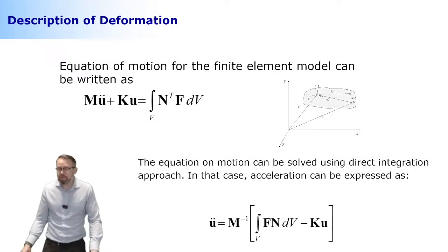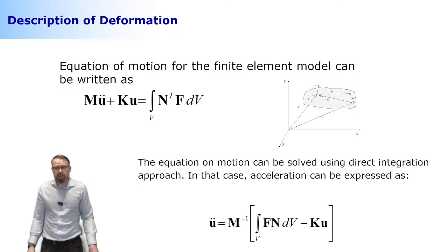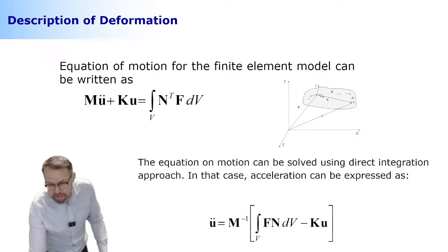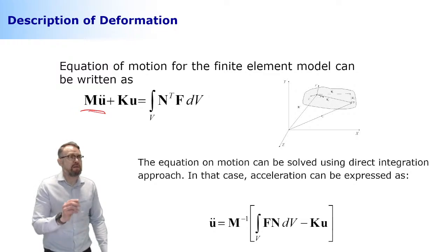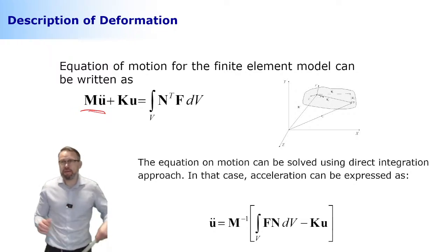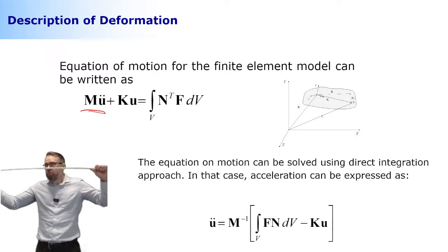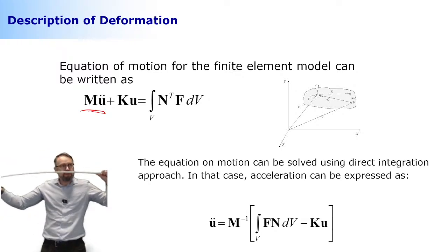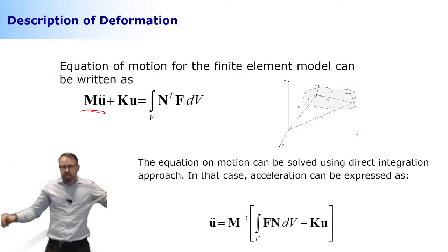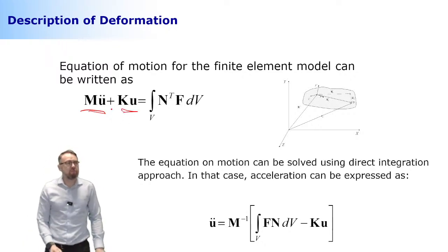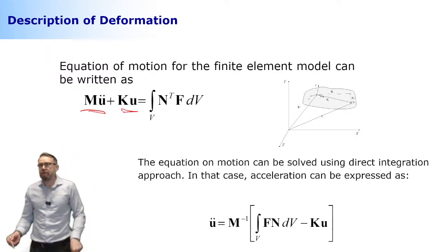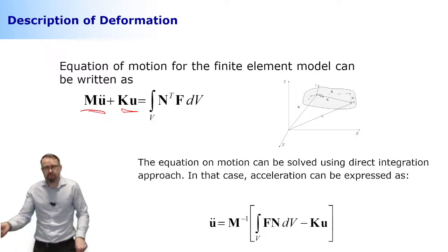Okay, here we are. This is where we are able to express this. This is mass multiplied by acceleration of nodal degrees of freedom, called inertial forces, but limited to small deformation with respect to your reference coordinate system. This is your elastic forces, which is the stiffness matrix multiplied by nodal displacement. It's your spring, if you may.